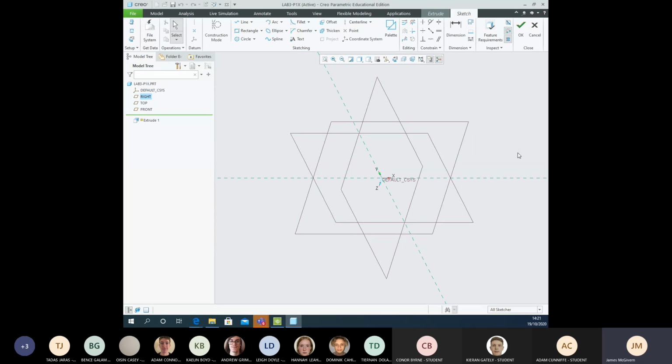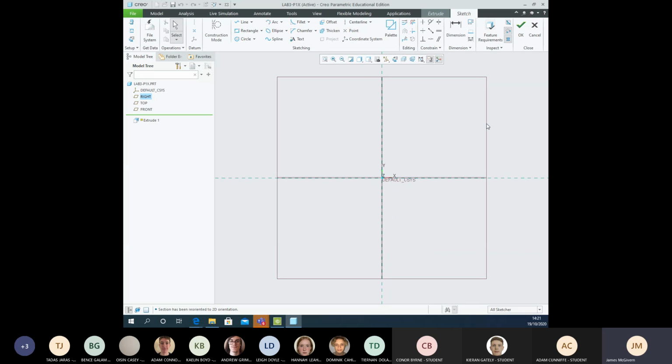And the exercise asked me to create a shape, a rectangle of 100 by 100 by 40 deep. So I turned the plane 2D, so it's facing me. So I'll put in the rectangle. I'm using a corner rectangle.